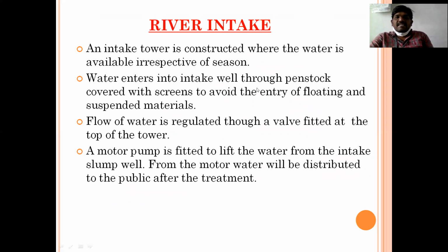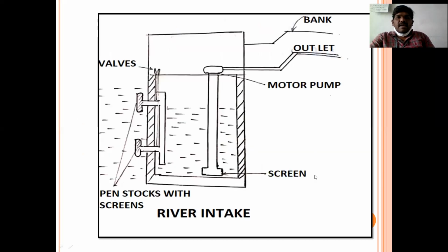Water enters into the well through the penstock covered with screens to avoid the entry of floating and suspended materials. A motor pump is fitted to lift the water from the intake sump well. From there, the water will be distributed to the public after treatment. Hope you understood about this river intake also.